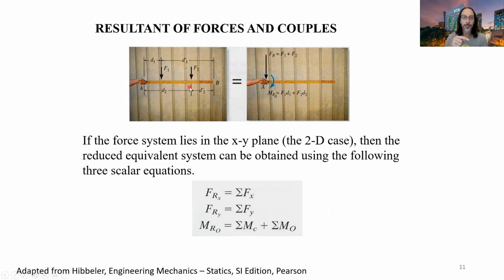If we had the problem like we had before with the workshop crane, we had a force at an angle, right? So we'd need to do both force in the y direction, as we have here, plus force in the x direction, to get the resultant forces. And then we also need to find the resultant moments of those forces that are applied.